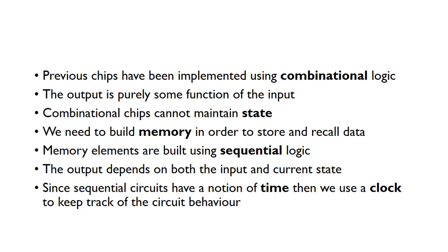And we build memory using sequential logic. Now with sequential logic, the output depends on both the input, just like combinational logic, but it also depends on the current state. Also, sequential logic circuits have this notion of time, and so we introduce a clock to keep track of the circuit behavior.